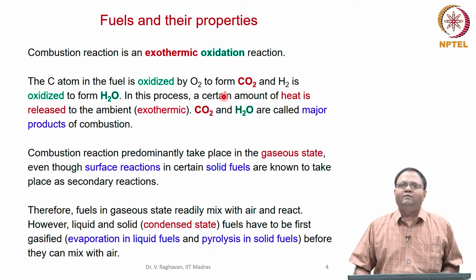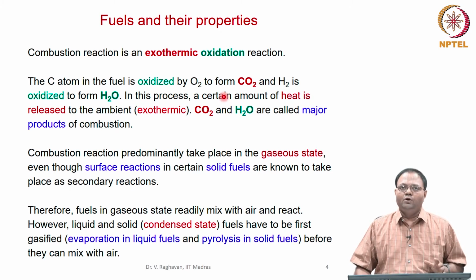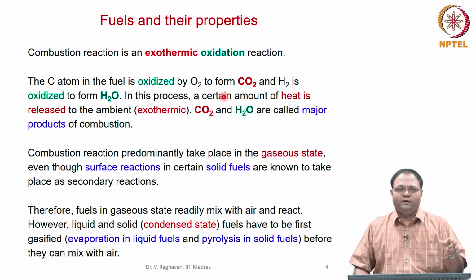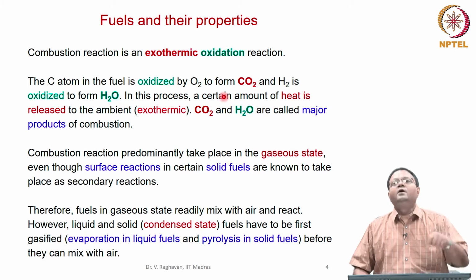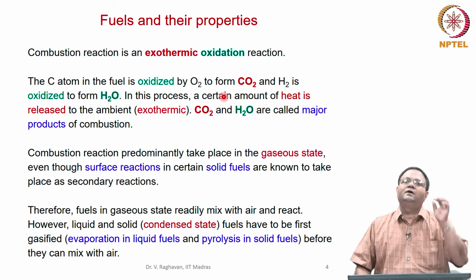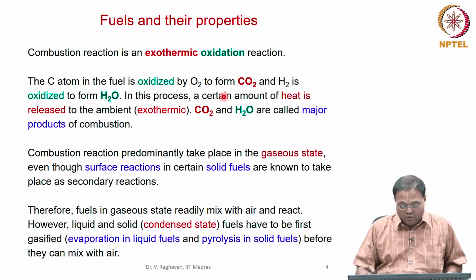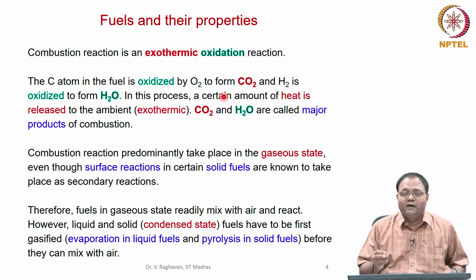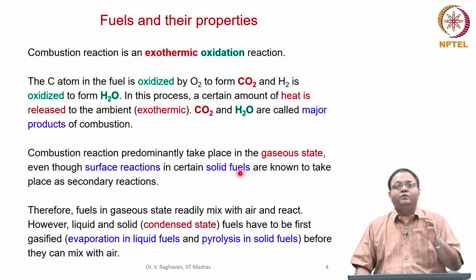If you have liquid gasoline and there is no way it is going to vaporize, it cannot react at all. Even if you supply cold oxygen inside and it bubbles through, it is not going to react unless it forms a vapor cloud, the vapor mixes with the air, and gaseous phase reactions are possible. Then only can it react.